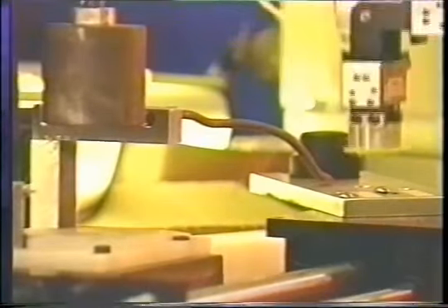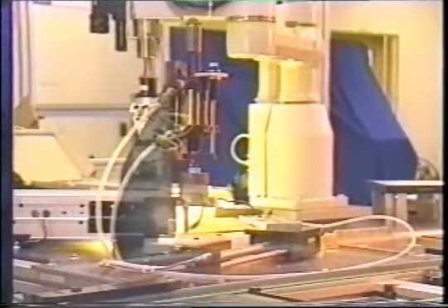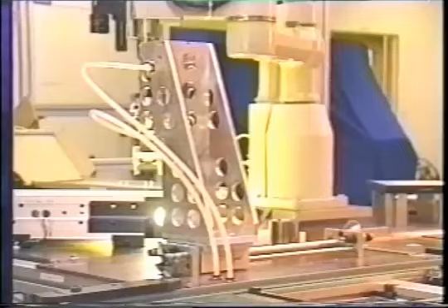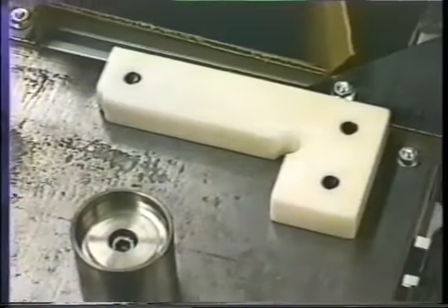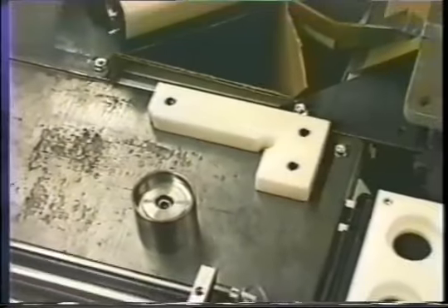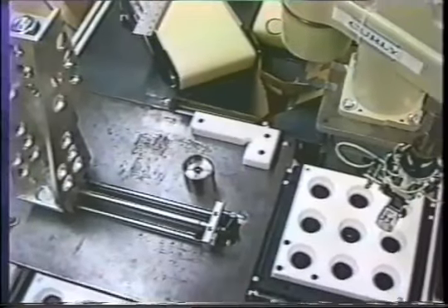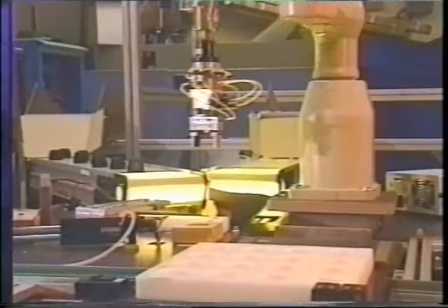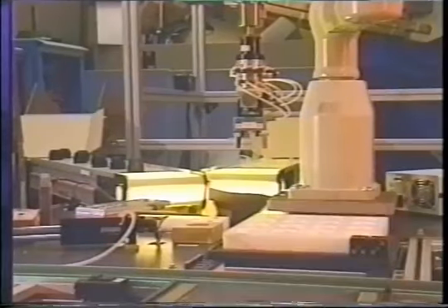Specialized hardware is required for assembly tasks which cannot be easily performed by the robots. This hardware is fixed onto modular assembly tables that are easily exchangeable, allowing the work cell to easily switch between products. The modular tables are outfitted with a set of precisely positioned registration points, which the machine vision system uses to quickly register the work tables into the robot's world coordinate system. This eliminates the tedium of reteaching assembly hardware locations. The same approach is also used to register incoming conveyor pallets.